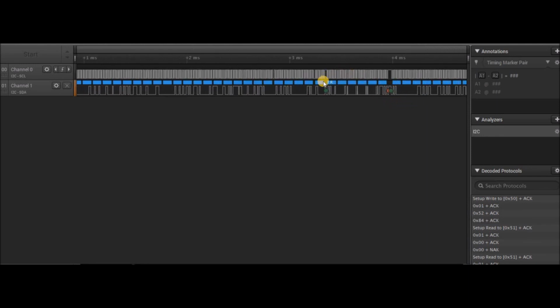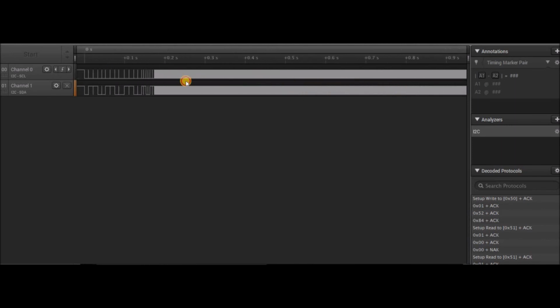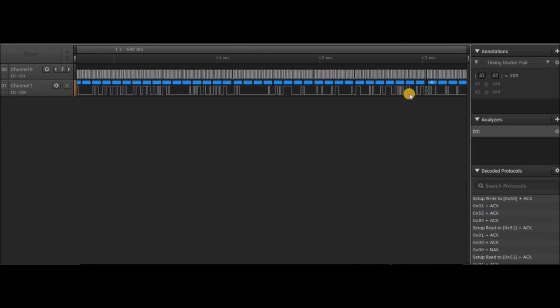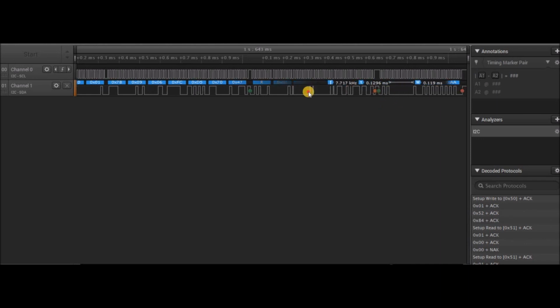So the master can send a block of data, poll its status just to make sure that everything is in order, and also that the slave has really received the amount of data which we expect. This is repeated until the master has sent all of the slave information, and the very last thing that it does is commands a reset. Here is the last polling to check that everything was okay.